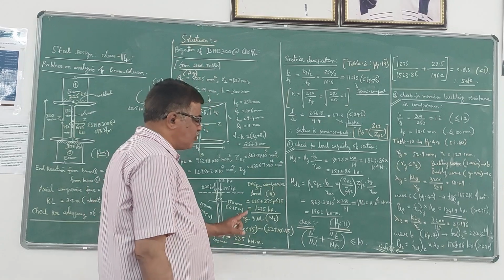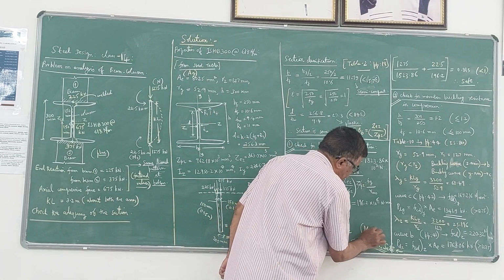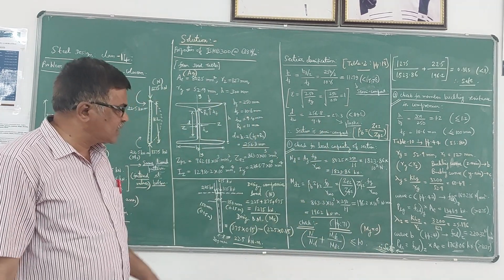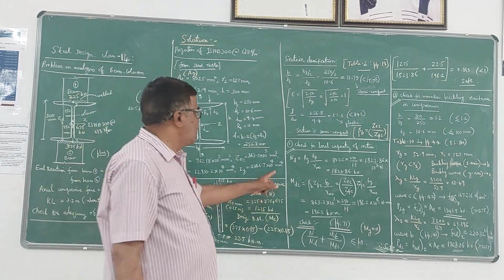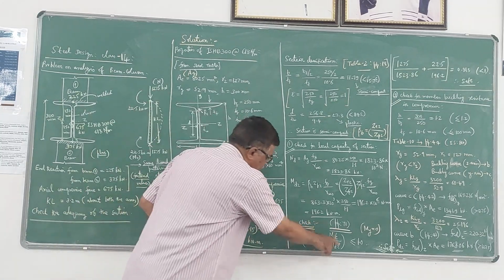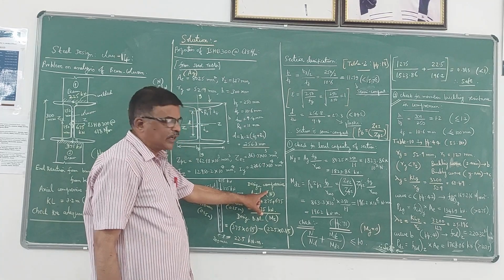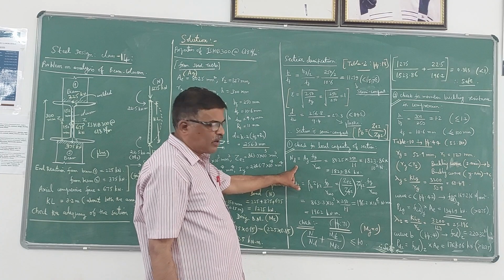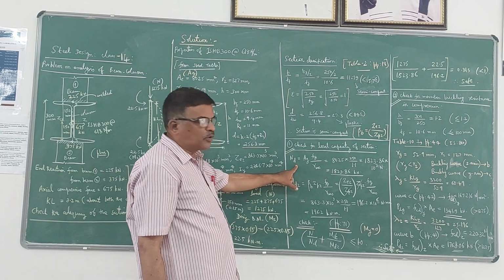So here, since My is 0, so this equation we are using because in this problem moment is acting only along one direction, along z direction. So it's a uniaxial bending case. Now here N is this value. To check that we need 4 values here. N is this 1275 kN total actual load acting on the column, and then Nd we have to calculate using this formula. It is the design compressive strength due to yielding.